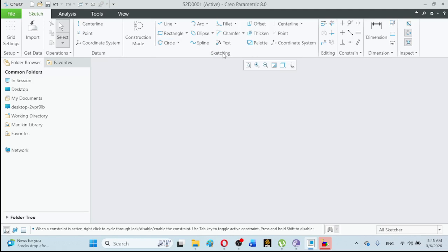For example, here in the sketching command, we learned in the previous lab session that this last column defines 3 construction type commands. For example, this is construction center line, this is construction point. So we can use this construction point and randomly draw 3 construction points anywhere on the screen. For example, here this is the first point and this is the second point. This is randomly drawn, and the third point can also be random, but it must be remembered that the third point